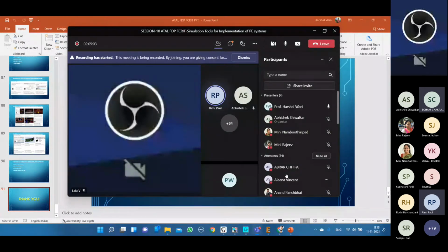Okay, ma'am, so basically you are using NI's Multisim and Altium Board. It's also a nice software to have; I wanted to integrate it here too, but I could not. Multisim is proprietary software by National Instruments. When you make the whole schematic in Multisim, you have an option to export it to Altium Board. The whole schematic which you have in Multisim will be exported to Altium Board, and in Altium Board you will find all the footprints.